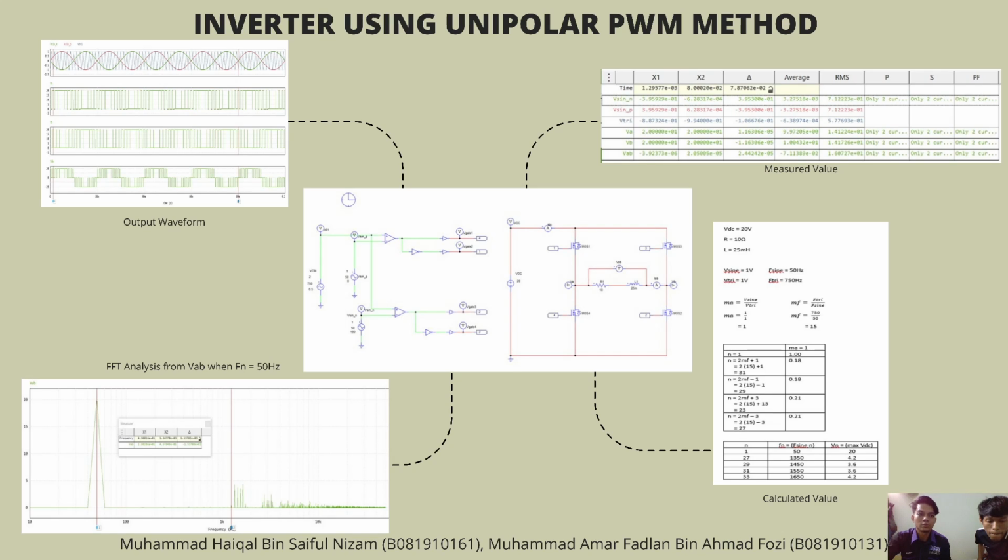The input DC voltage in a PWM inverter is constant in magnitude, while the output AC voltage has controlled magnitude and frequency. Most PWM is generated by comparing the reference waveform with a triangular carrier waveform signal. A sinusoidal waveform signal is used for PWM in a DC to AC inverter, where it is used to shape the output AC voltage to be close to a sine wave.